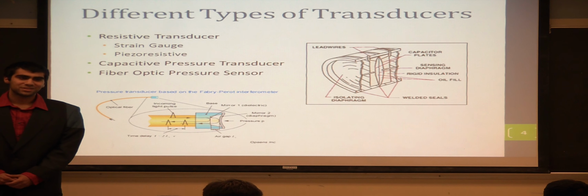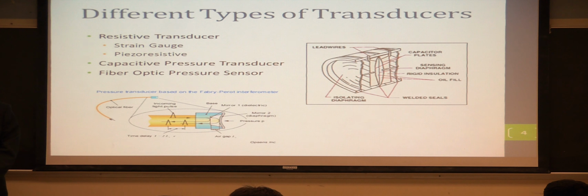The fiber optic pressure transducer uses a mirror which is attached to the diaphragm of the transducer, and once a strain is applied to the diaphragm, the mirror changes position, and the displacement in light seen in the fiber optic cable is seen by an optical sensing element and output as a voltage potential.